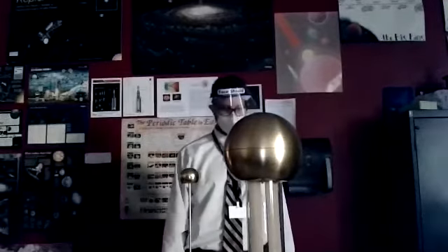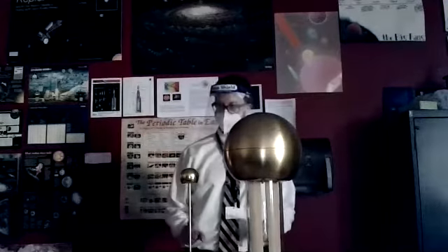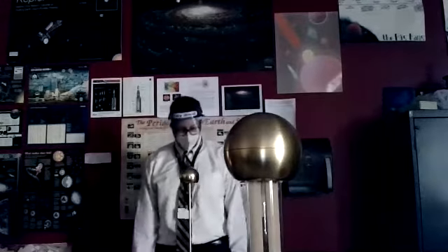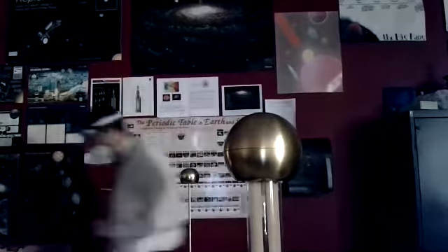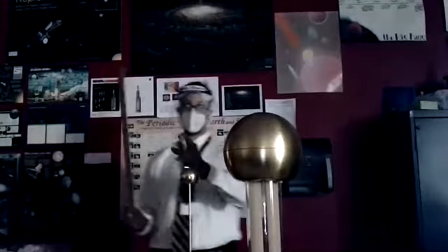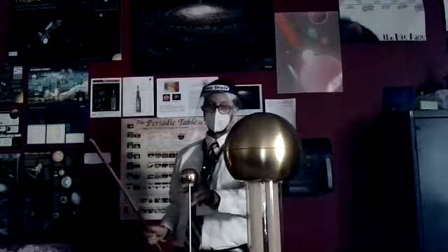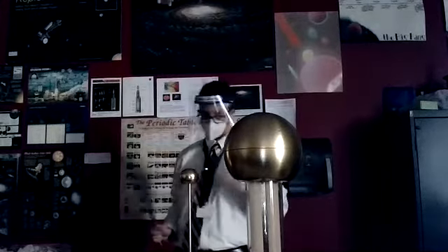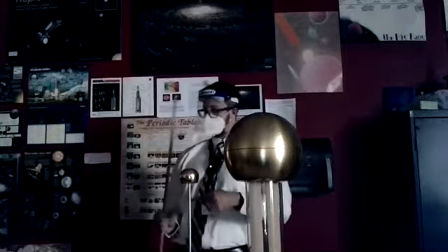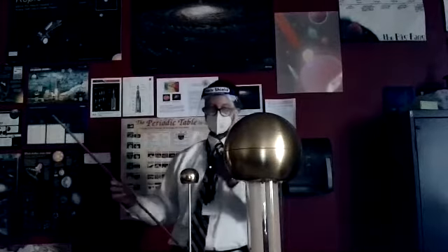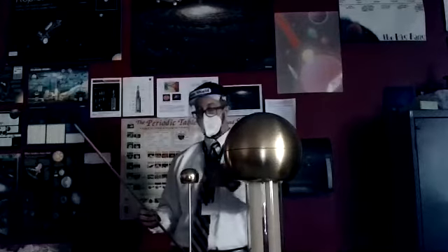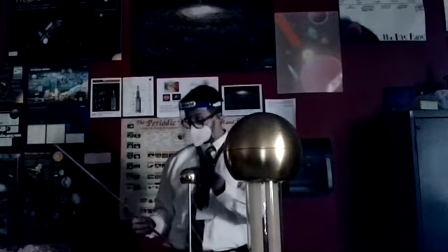Okay. Anybody else want to be shocked here? Let's take the measurements that we need. You may have noticed that the discharge occurred even at this distance here. If you let it run long enough, it will start to conduct across this distance. So you just measure from this surface to that surface, and that would be the distance d where we can see evidence of electrical breakdown.